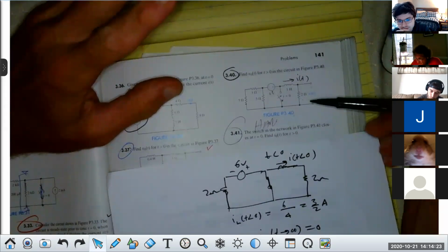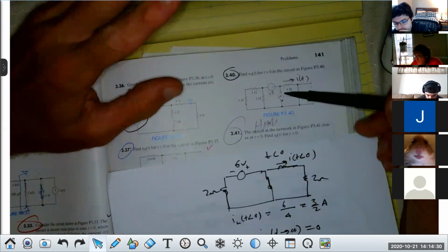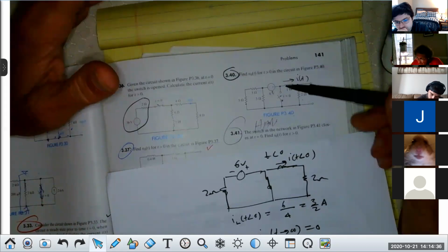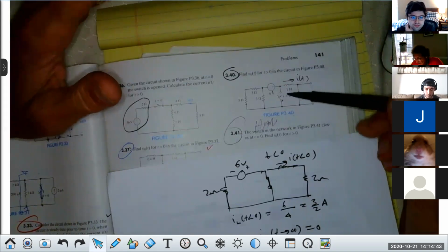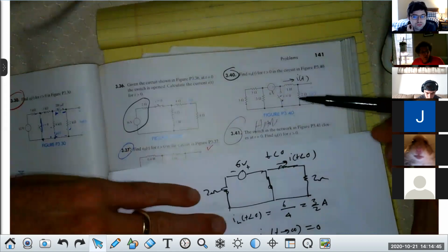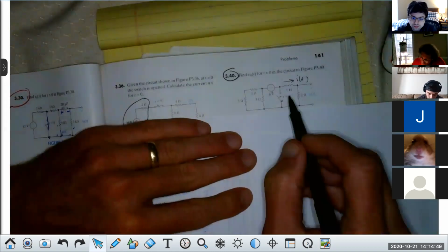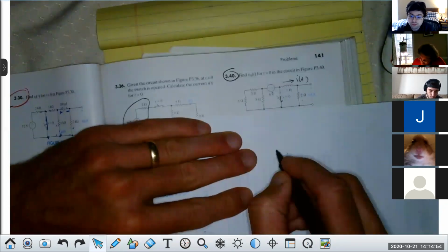All right, now, the next thing I want to do is, what do we need to get next? We need to get the Thevenin equivalent impedance or resistance, whatever you want to call it, across the inductor after it's removed, right? Y'all agree with that? Now look, after it's removed, for t greater than 0, that switch is closed. So really what I have is this.